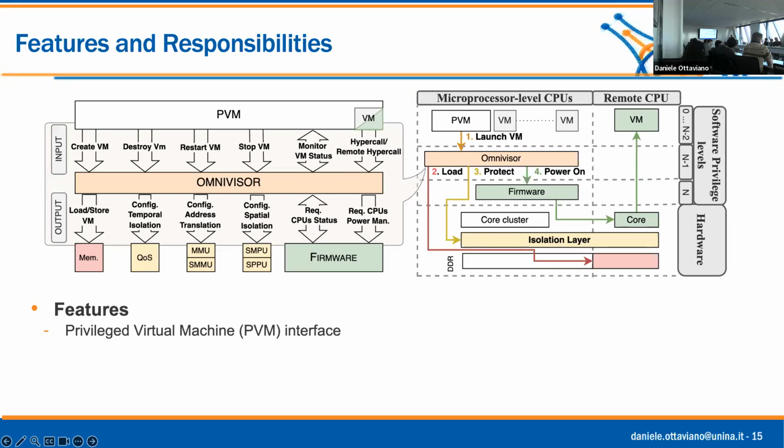I don't know what remoteproc is. Well, remoteproc is a driver of Linux, which is used for loading binaries into coprocessors like this one, right? There are many of these heterogeneous systems that have an M4 or an M0 on chip, or an R5 like this one. And the driver that people use is the remoteproc driver of Linux to load ELF onto those and launch them. The moment you do that, it's game over. That thing is the king of the system.